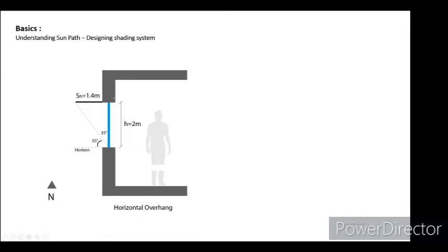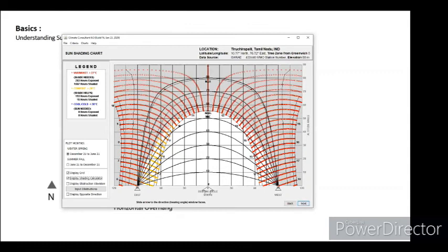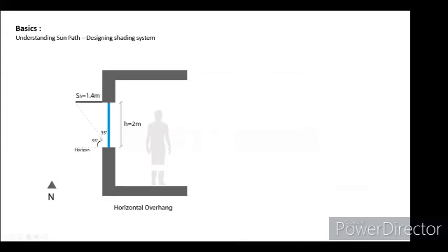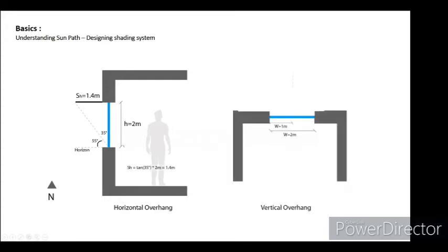So if you have a window, let's say 2 meter by 2 meter in height and width, you have to put this angle at 55 degree so that you can reduce the amount of hours exposed. That means we have the length and we have the remaining angle of 35 degree. We can just use a simple trigonometric calculation to find the length of the horizontal shading system.